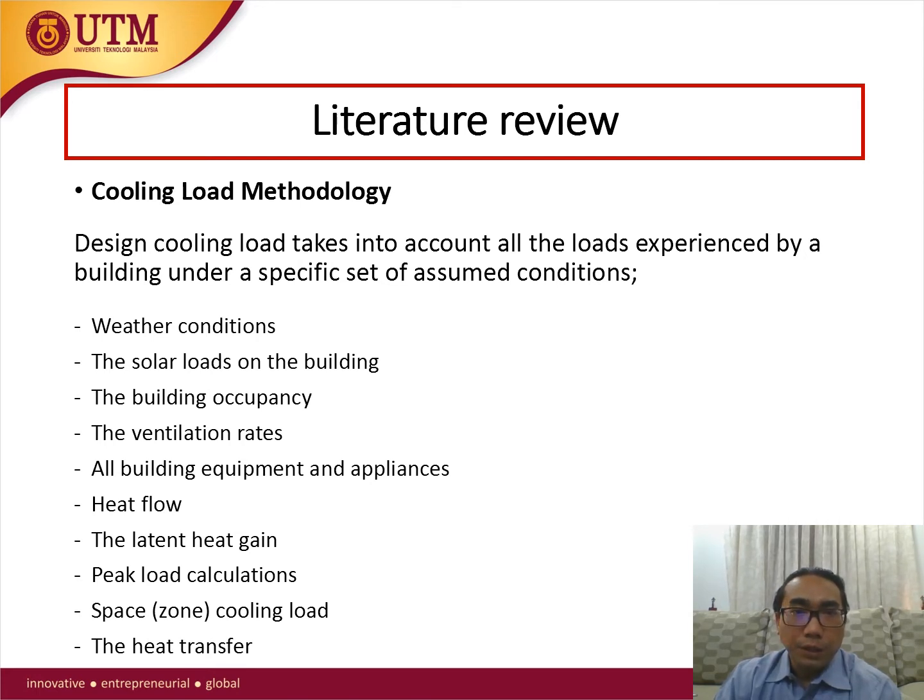Peak load calculation evaluates the maximum load to size and select the refrigeration equipment. The energy analysis program compares the total energy used in a certain period, which varies among various alternatives, in order to determine the optimum one. Space zone cooling load is used to calculate the supply volume flow rate and to determine the size of the air system, ducts, terminals, and diffusers.